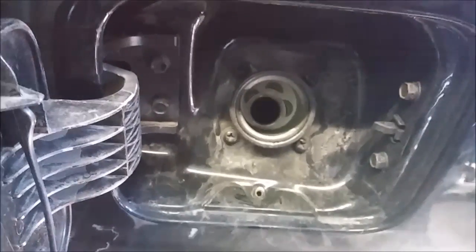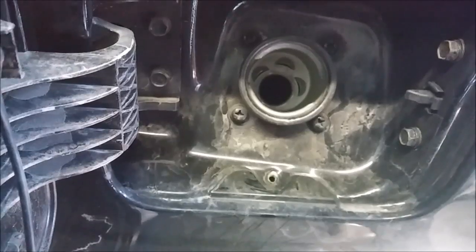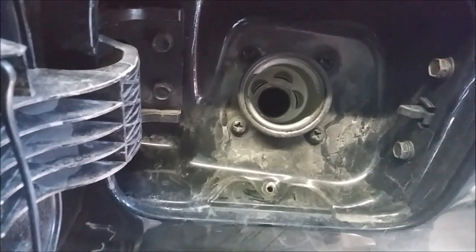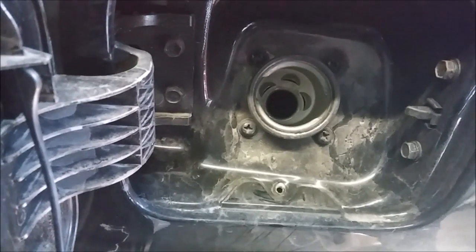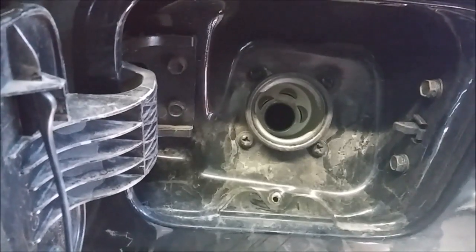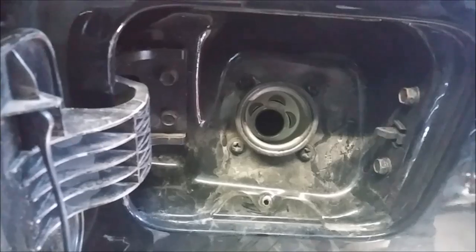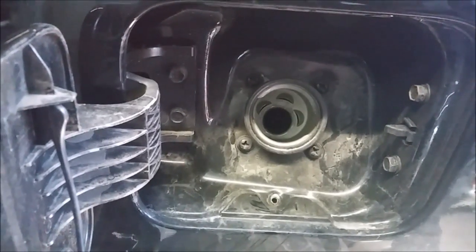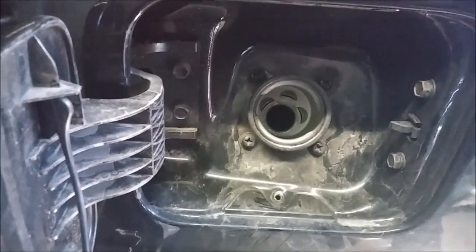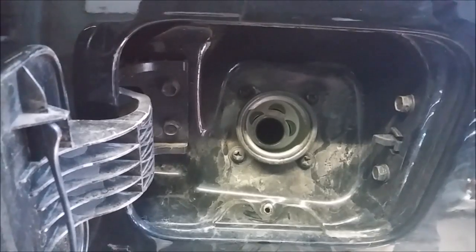And what I'm looking for is smoke to come out. Smoke coming out of this is telling me that our connections are good, and we are in fact pumping smoke into this system. On some of these vehicles, you won't get smoke back there from testing at the purge solenoid. You need to hook up somewhere on the canister. So I've just got this cap off currently, and what I'm waiting for is smoke to start billowing out of this, and that's really going to tell me that we have this system filled up with smoke, and we can trust our smoke test from that point.